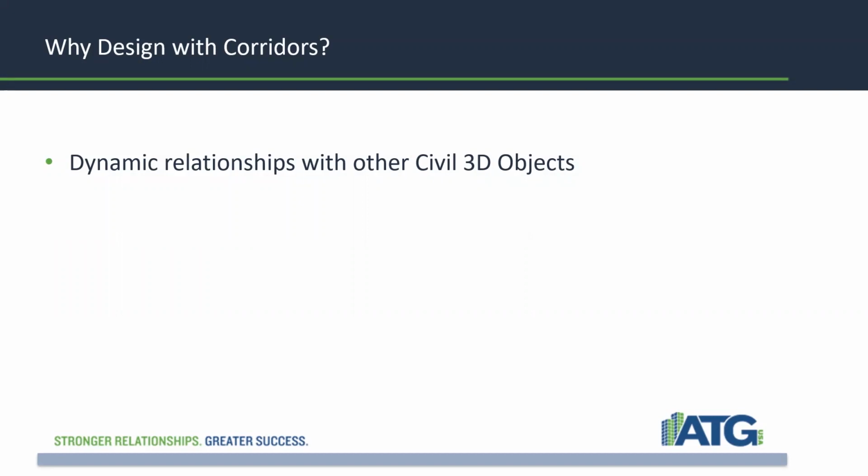And the reason why we'd also want a corridor over just a simple grading object for our final surface is because we can generate a tin surface for any of the design components based off of our subassemblies. That means that if I want a datum surface, I can generate that through my corridor. I could also find out where the top of my subbase or the top of my base or any of those other surfaces is, I can just go ahead and grab those. And again, it's going to be dynamic to all of the data that comprises our corridor.